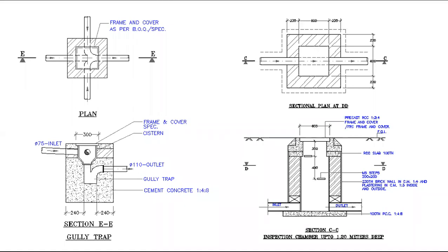Suppose you are coming from under the plinth beam, you have to see your site only. So minimum how much depth can we connect? 600 or 500 or 400? Minimum 300. Because in our site, maybe pavement or some hard surface will come.